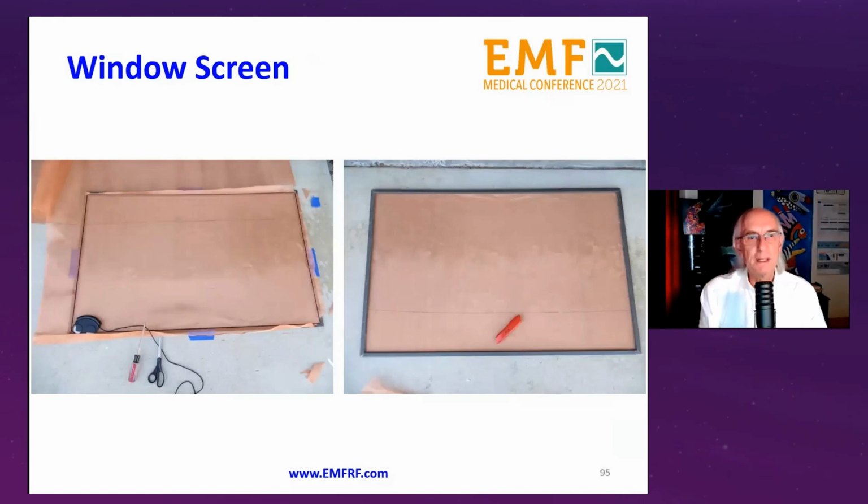There are also a lot of self-made tools. For example, what I did here is I took a window screen out, which is a fly screen, took that mesh out and put a copper wire mesh in here. And now I've got a fly screen made out of an RF shielding material. Well, maybe it only covers half the window because only the movable part has a screen, right? Well, you could make this larger than your window, overlapping the entire size of your window, and attach it to the outside of your building, and then you have a very highly effective shielding material to deal with your windows.